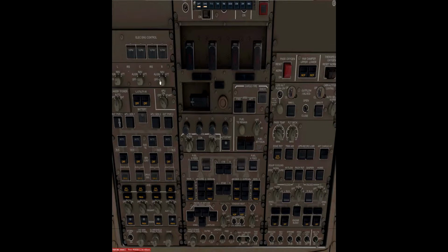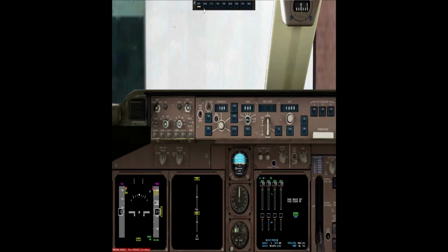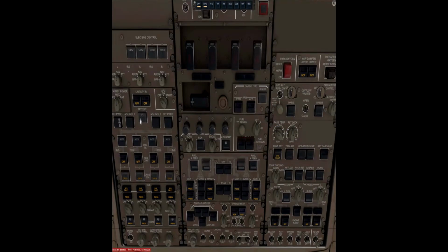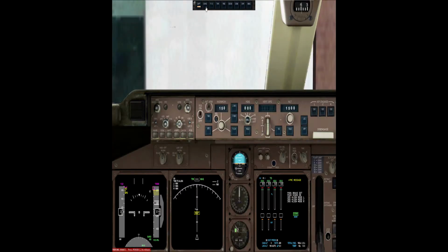Now we're going to switch the IRS, the inertial reference system, off and then back to nav if they're not already off. And then when we come down here, it should come up, there it goes up, and it goes into align mode. I've got it set up for a minute or something like that. Once it's all aligned, it should automatically bring the artificial horizon and stuff up on there. So anyway, we go to here, that will be it bonging to tell me that it's done.